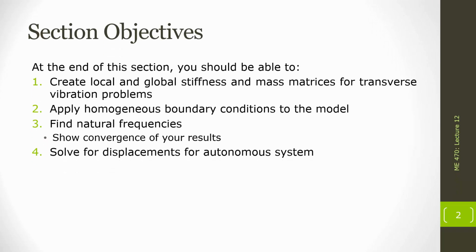At the end of this section, you should be able to create the local and global stiffness and mass matrices for transverse vibration problems. You should be able to apply homogeneous boundary conditions to enforce zero displacements and zero slopes in the model. You should be able to find the natural frequencies and show convergence as we add more elements to our model. And finally, you should be able to solve for the displacements in autonomous systems.